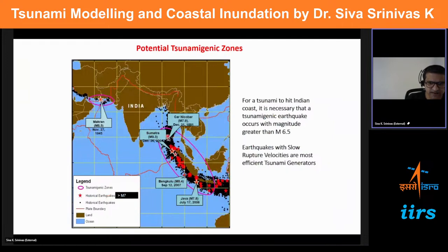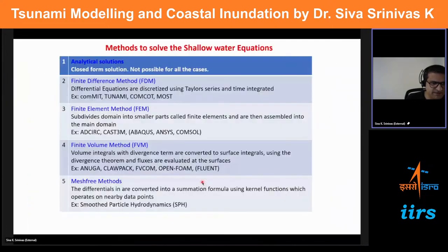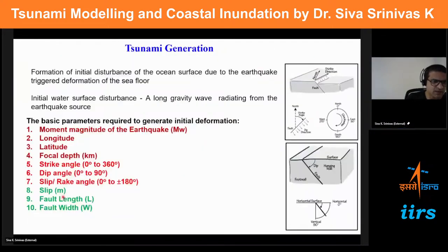See here, all the black dots and stars are the historical data. Data is available since 1881 or so. For those data, all the seismic fault parameters are available. So in real time, whenever we have longitude, latitude, focal depth, and moment magnitude, from the historical database we pick strike, dip, and rake, these 3 parameters.